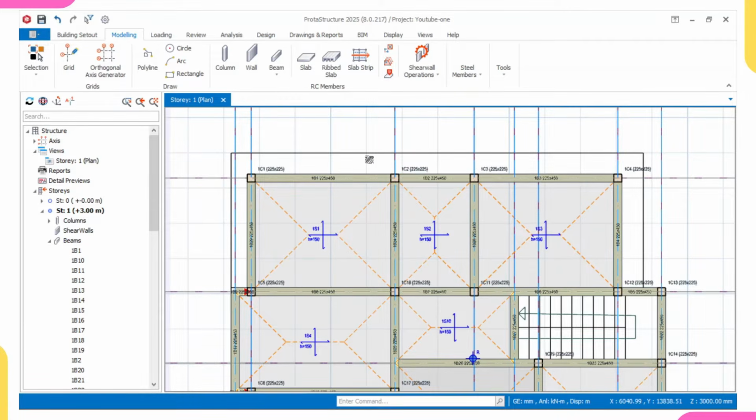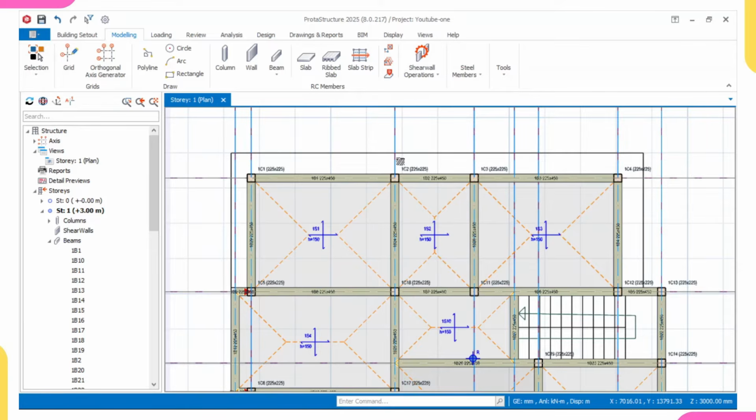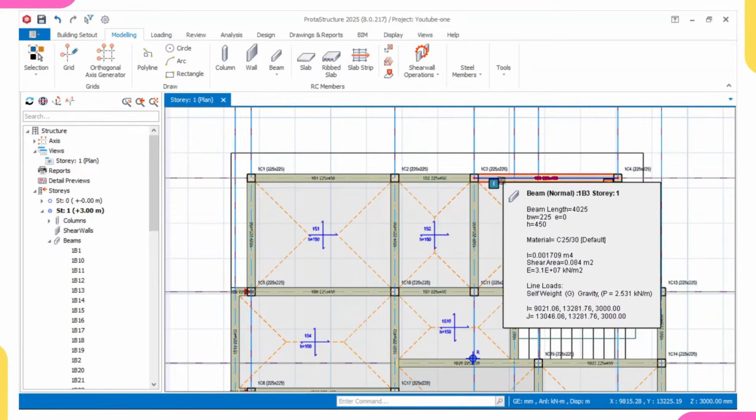Something like we'll be having positive 30 kilonewton here, and this side we're having negative 30 kilonewton. If you sum both of them, since one is positive and the other one is negative, you'll be having 0, because the summation of moment at any point is equal to 0. The same thing with here. There is a moment like this. That's if you can remember your structural analysis, that's in your university level. We're having a moment like this and also a moment like this. One of the moments will be positive and the other one will be negative, for example, positive 20 and negative 20.